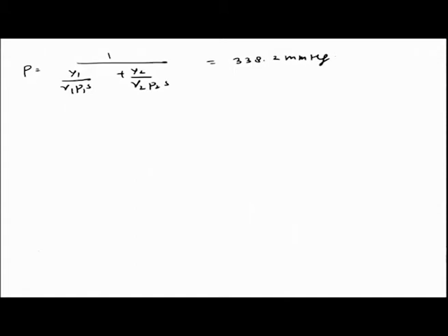mmHg. So it tells you that the system pressure is greater than the dew point pressure and less than the bubble point pressure. Okay, so basically it tells you it is lying in between. And thus this would mean that this is phase segregated, which was not able to be captured by the Raoult's law. So you again write down the material balance.